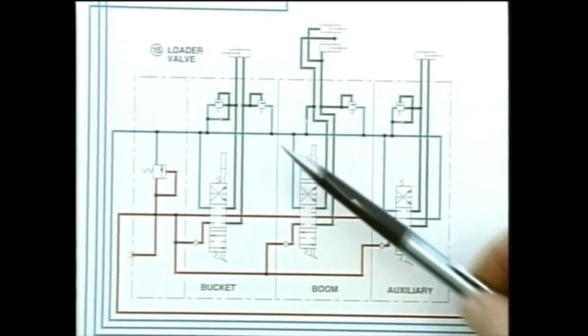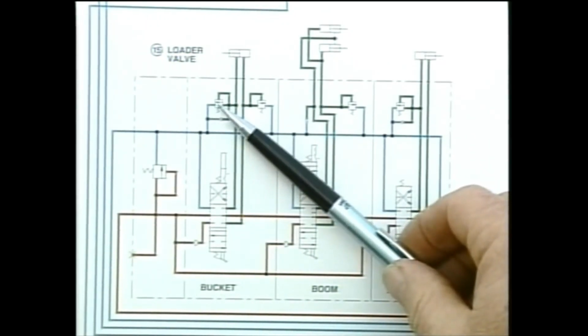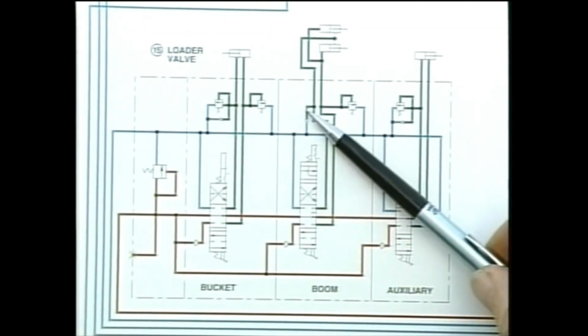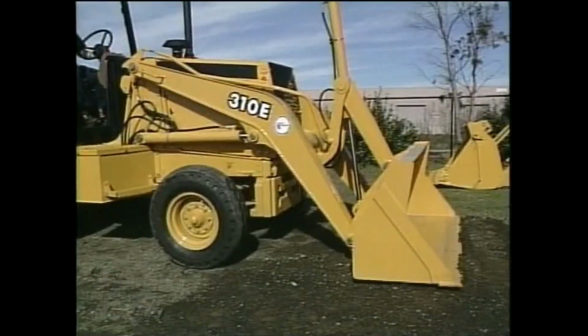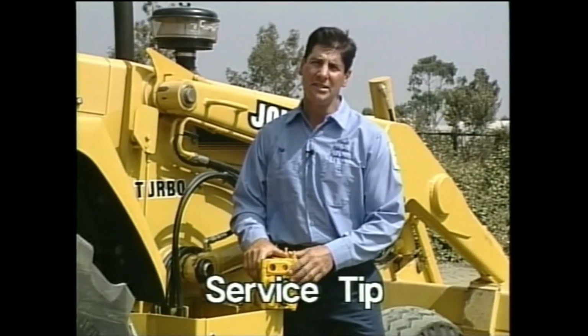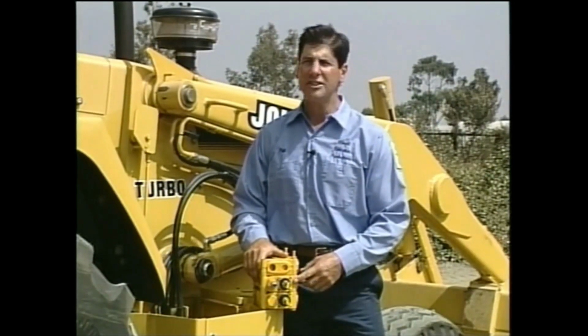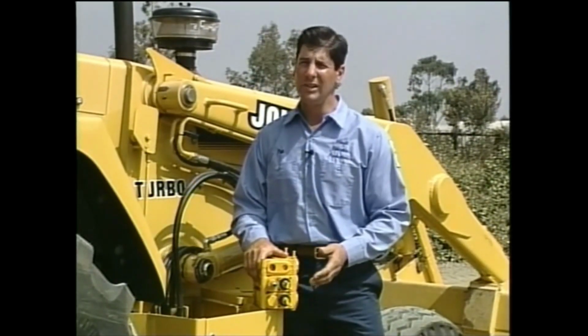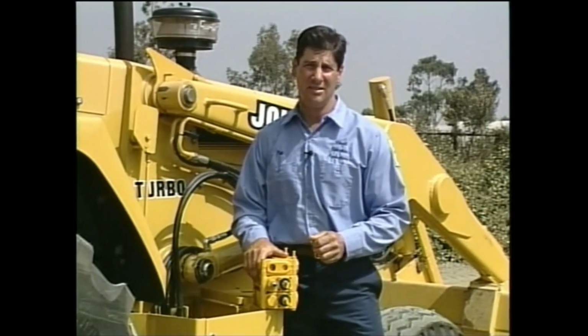If you suspect a circuit relief valve is the problem, select a different directional control valve that does not have a safety circuit relief valve and retest the system pressure. In this case, when the problem is isolated to only one circuit, that circuit's relief valve should be tested or adjusted before the system relief or the hydraulic pump is tested.